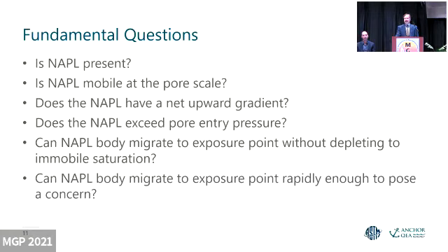And if we conclude that it is mobile at the pore scale, then we go into a series of questions that help us interpret whether or not the NAPL has the ability to move at the NAPL body scale. Each one of these questions can be answered by collecting specific types of data and then interpreting those data in a systematic way.